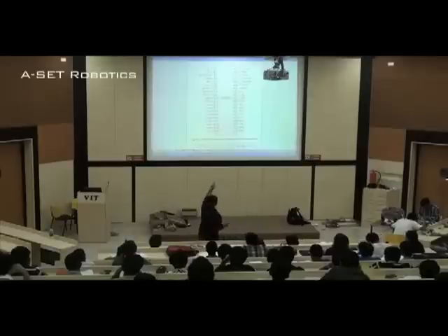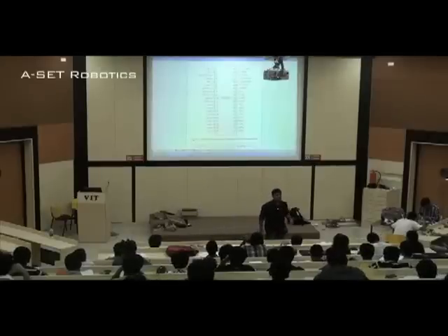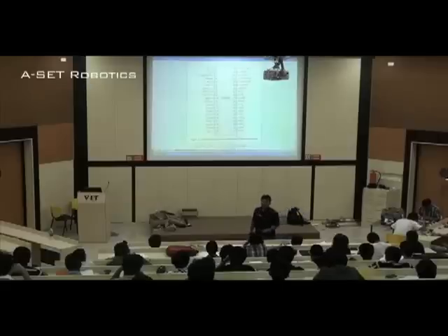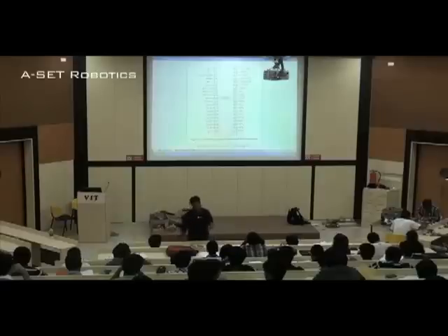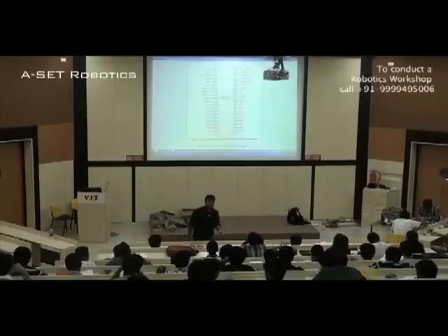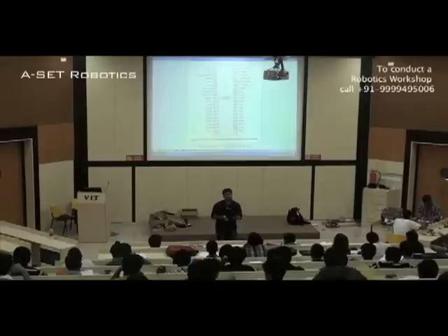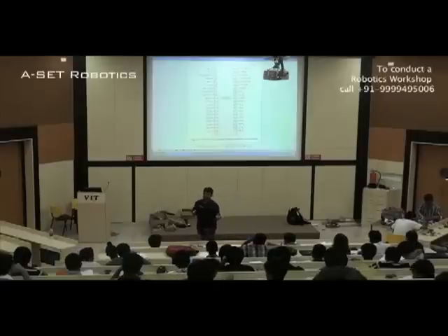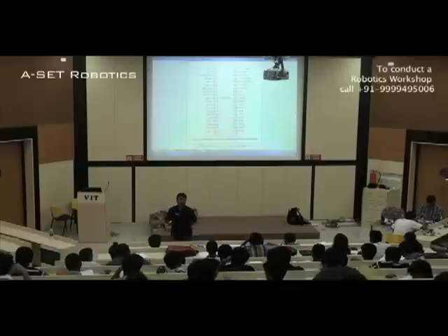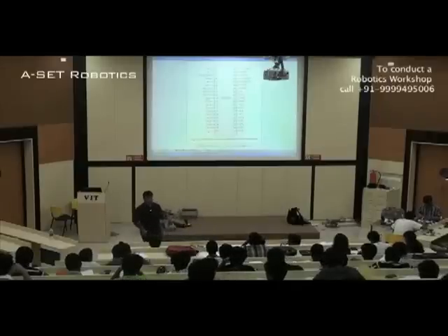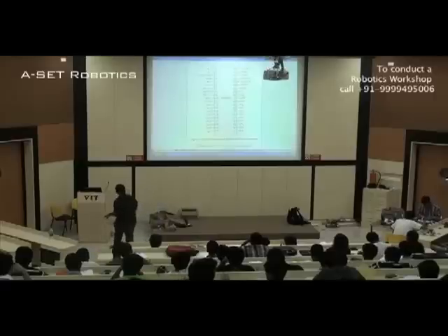So from this clock out, we give it to the synchronous devices that synchronize with the microprocessor, like memory, or any other device that synchronizes with the microprocessor. Because of that, we can connect it to the microprocessor. Otherwise, we would not be able to connect those devices to the microprocessor. So this clock out is a very important signal.